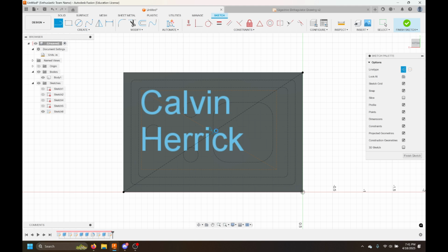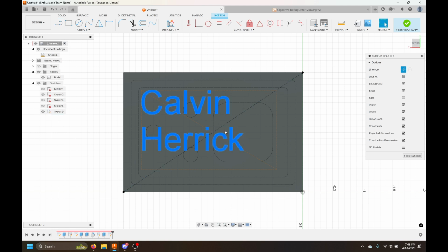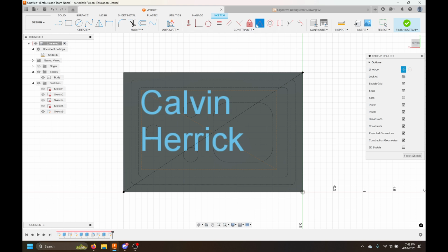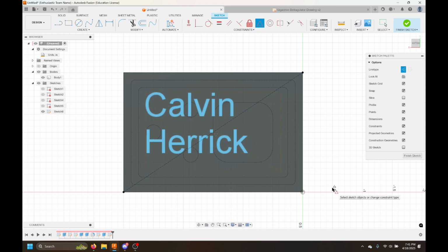And these make an X here. Oops, X marks the spot. X does mark the spot. Because we're gonna use the midpoint tool. And we're gonna say the midpoint of this line has to be the same as the midpoint of this line. And it's gonna put our box right in the center.